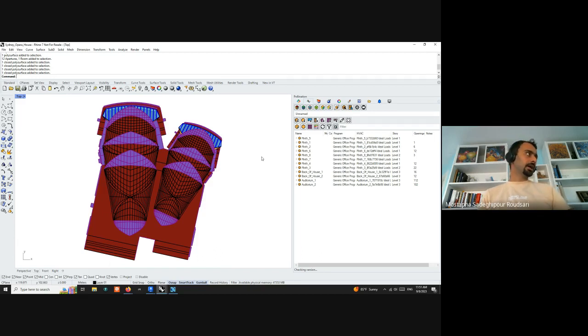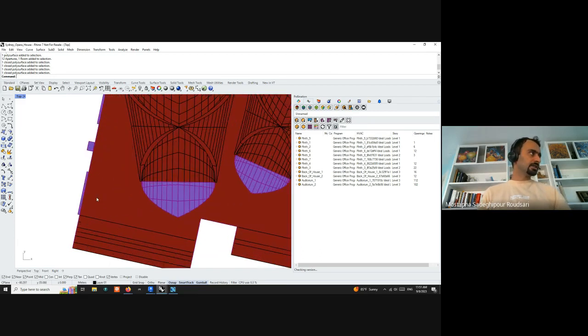The only limitation we have is if you have something like this and then there is a skylight. Because of how eQuest works with X and Y, that skylight will be rotated to be orthogonal. Again, from my end, that's not a very important issue. But if you think it is, let us know, and we can fix it. We can do some additional math to fix it, but it was not on top of the list. Thank you. Any other questions? Anything that I missed, or anything else that you want me to show?